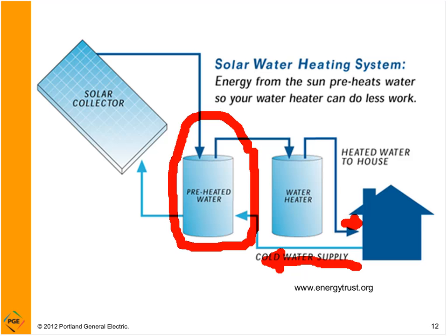So there's a very large delta in the temperature between what comes into the facility and what goes out of the hot water system. If we can take and preheat that cold water with sunshine, it can take a very large percentage of the need for heating up with electricity or gas and use the sun to do that. So that's the function of this preheat tank.